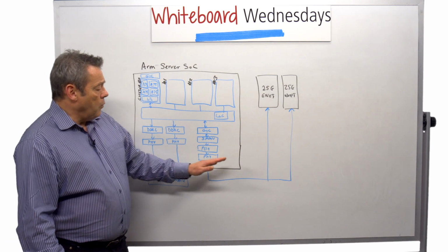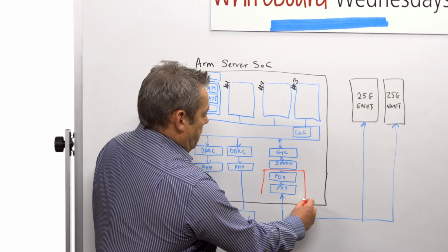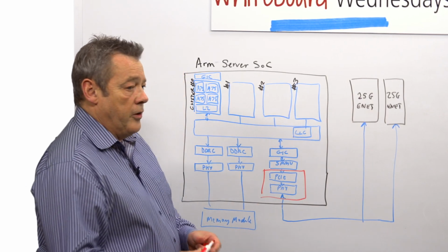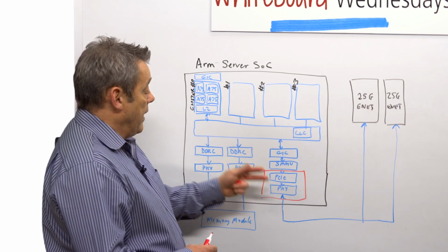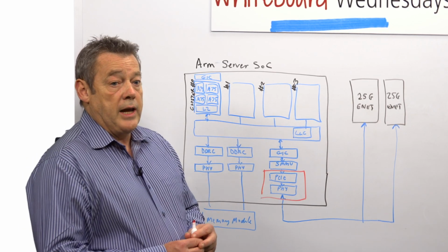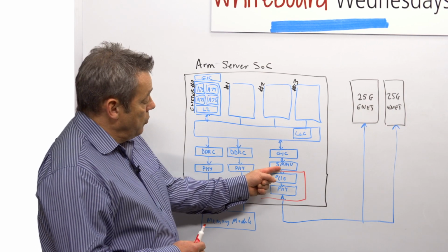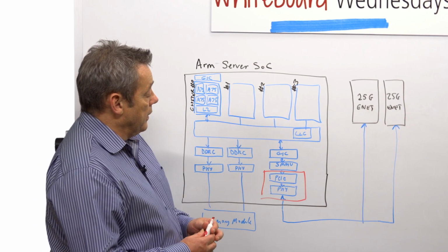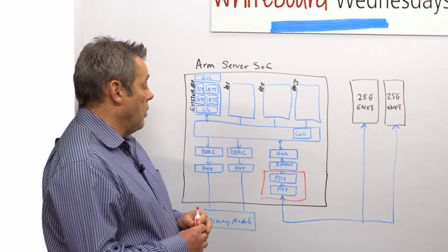And when we integrate the PCI Express IP, this block here, into the system, it's very interesting because in Gen 4 we have some very big additional challenges that have not existed before. And these are to do with a couple of components here called the system MMU and the generic interrupt controller.